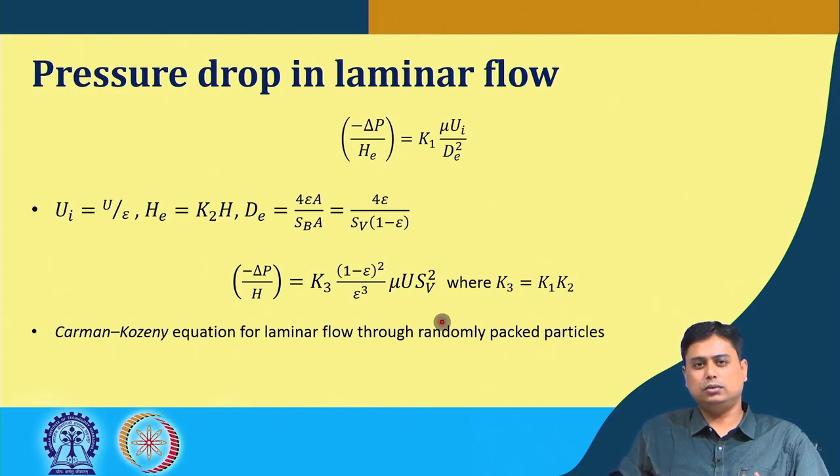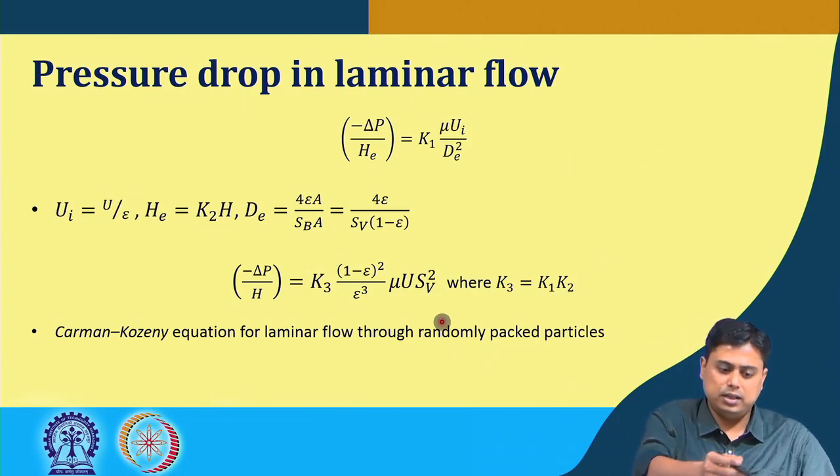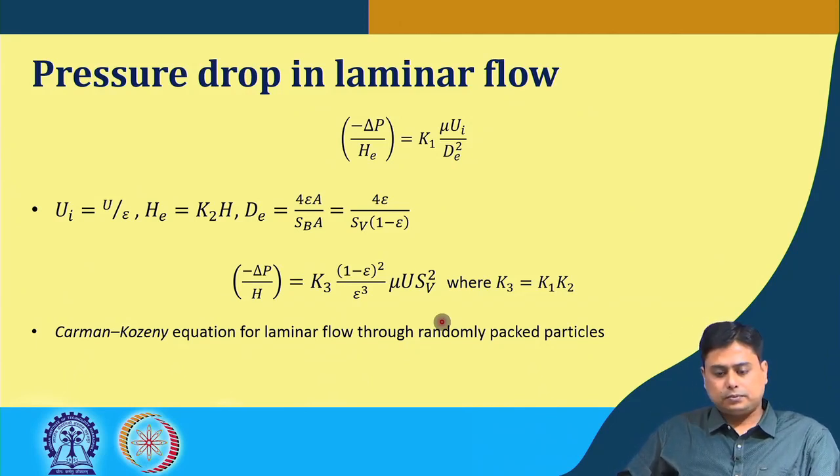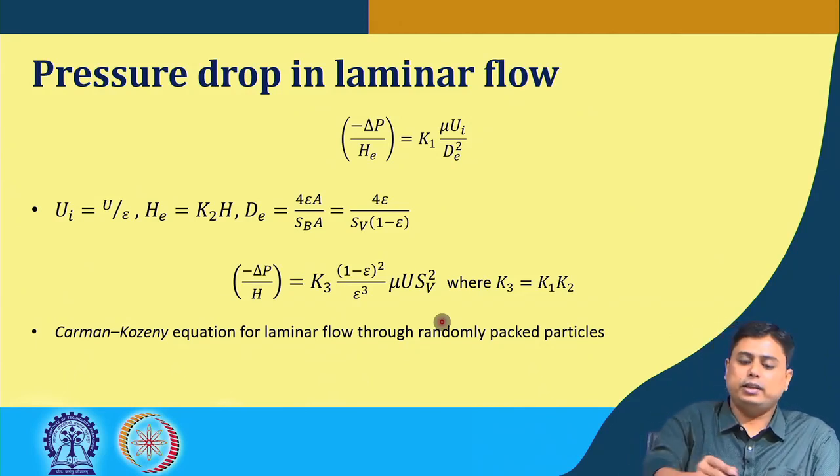Any kind of particle, when there is laminar flow through a stack of those particles, when a fluid is flowing, a single phase flow, the frictional pressure drop across that bed, or rather the pressure gradient, here it is del P by H that is written here, is given by this expression.